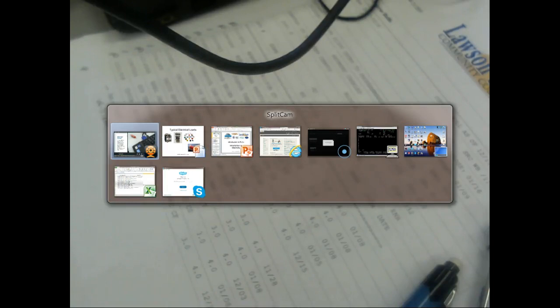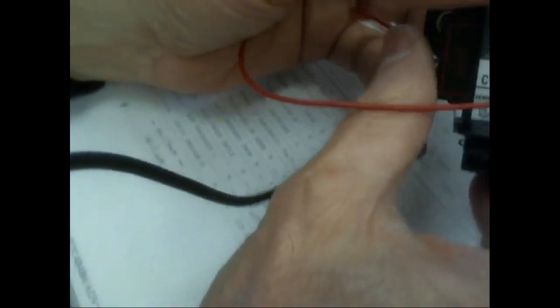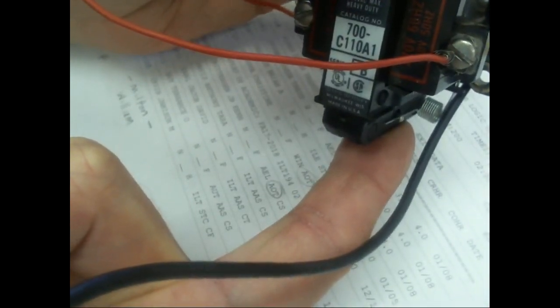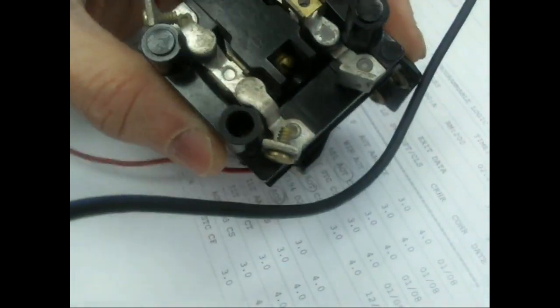So what if we take that same solenoid and we mount contacts on it? Oops, sorry guys, where's it at? So here's the solenoid right here. Here's the two wires that hook up the solenoid. This is that plunger that was my nail right here. We refer to it as an armature. So when I put power across these two terminals right here, it's going to suck that thing up like that, right? You understand? Everybody okay?